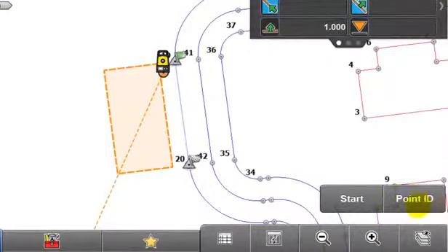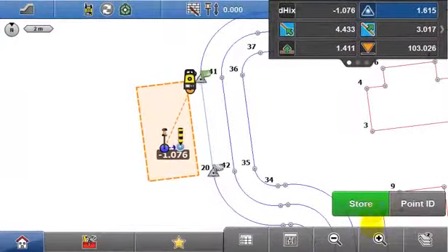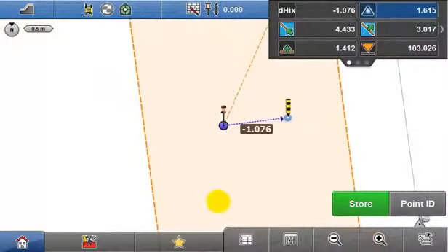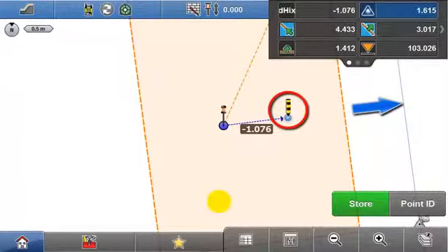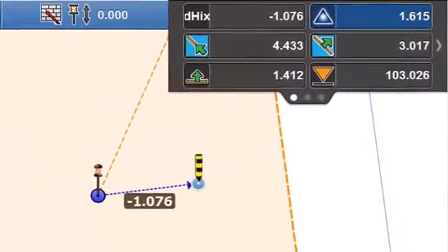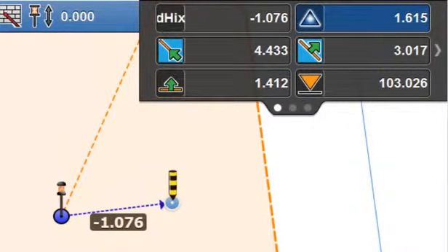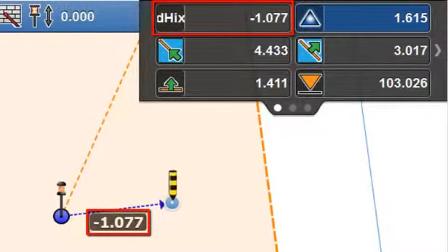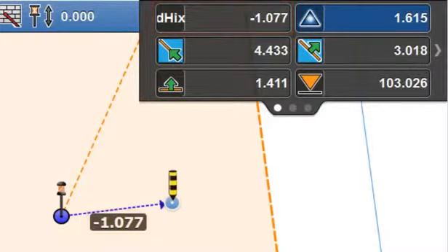Once measurements are initiated, in this example using a total station, the position of the prism is indicated on screen, in real time, along with the intersection point to the reference surface, perpendicular to the initial reference at the current measured height. As well as the prism position being displayed, key measurement data is displayed in the info panel, including the cut or fill value, that is the vertical distance between the current position and the designed surface. This value is the horizontal distance between the current position and the reference surface, perpendicular to the initial reference element.